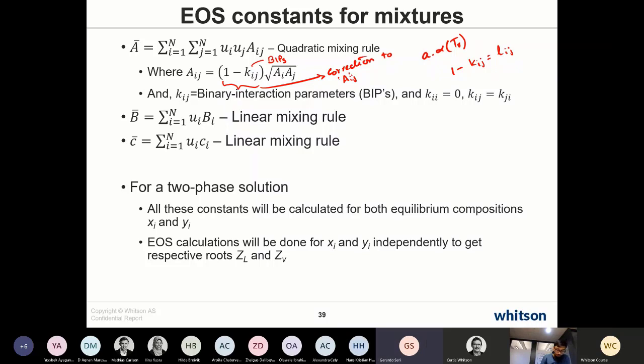Just a question for me to clarify. So I get this that within C1 to C6 you fix your vapor pressure, and then you use the volumetric correction to get your densities. But when you start going to heavier components, your vapor pressure is not really well known. It's a range, right? Yes. So then you end up with 2 variables. You have the volume correction that is moving on an X, let's say, and then you end up with these binary coefficients that can move you on the Y. And you still respect the fugacity, basically. So how do you know which of the 2 to go?